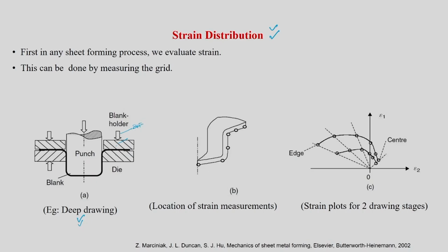Okay. And you know that there is no restriction for the movement of sheet in the radial direction. It moves actually, but the only restriction is through friction. Otherwise there is no constraint. So finally you are going to get a cylindrical cup like this. You have seen this example before. Okay. So now I have a partially drawn cup, similar diagram we have seen before. I have just shown you one sector of that. So this you know is a flange region, this is a cup wall region, and this is a cup bottom region. That is known to you.